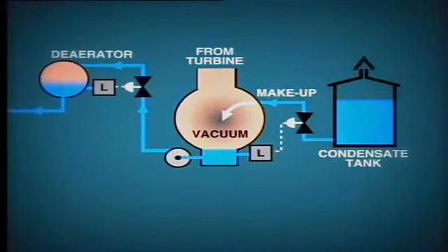In a similar manner, the flow of water into the de-aerator is determined by this particular control valve, which is controlled by signals from the level transmitter at the de-aerator. Let's see how this simple arrangement works during a plant shutdown.